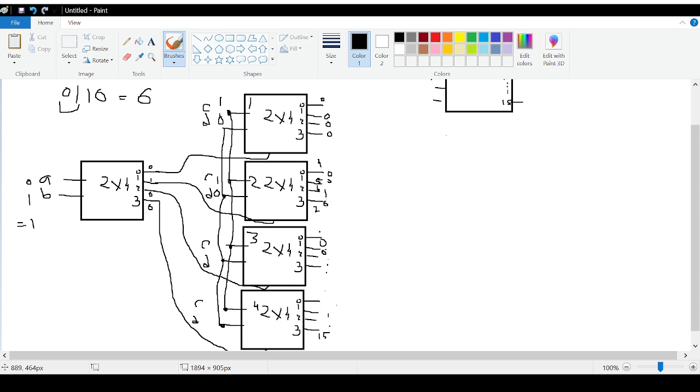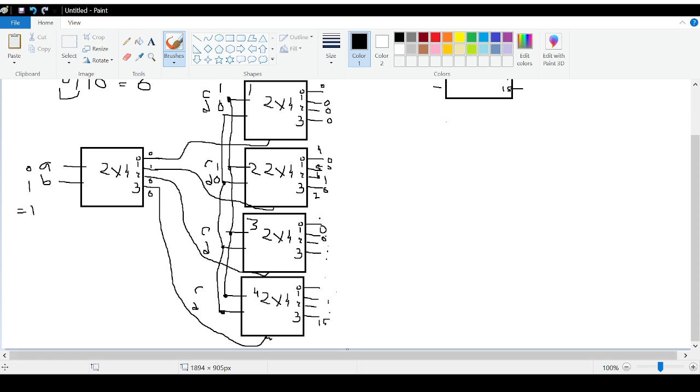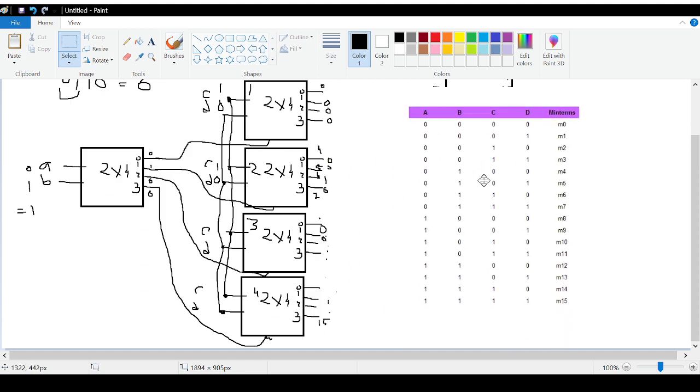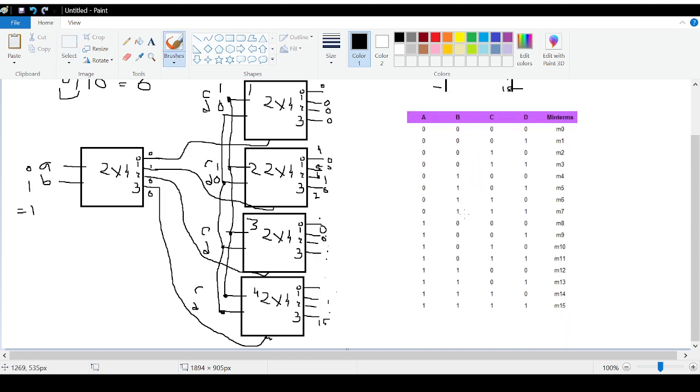Okay, so line 1 comes out of line number 6. So overall this is working like a 2 to 4 decoder. Does anybody have any question? So you might be wondering how did I come to this approach? Now the gist is, you need to see that when I'm given a 2 to 4 decoder, at a time for each decoder I get 4 outputs.